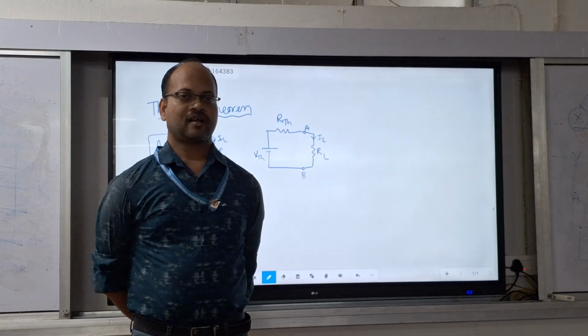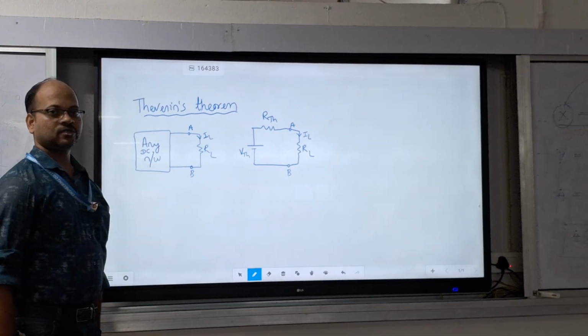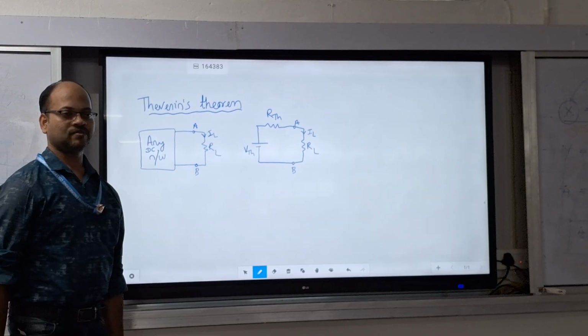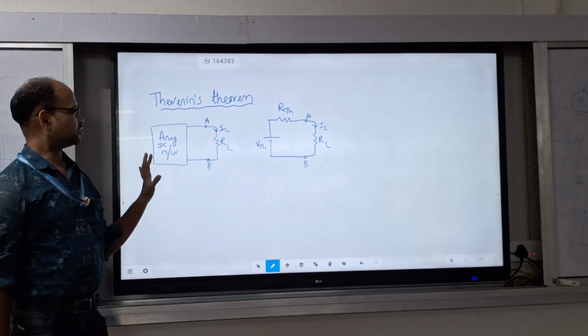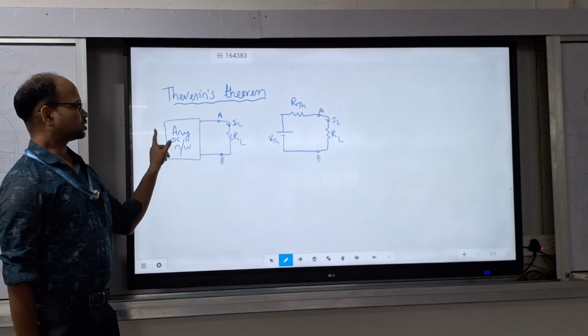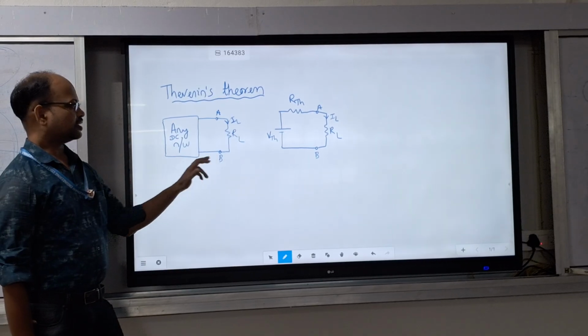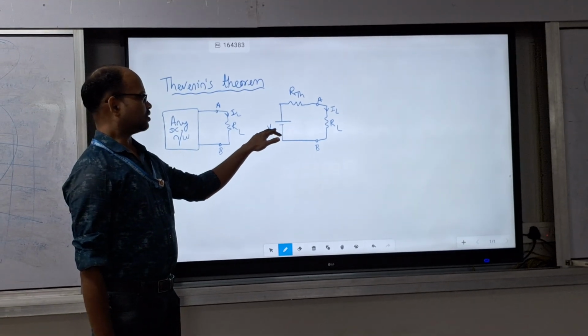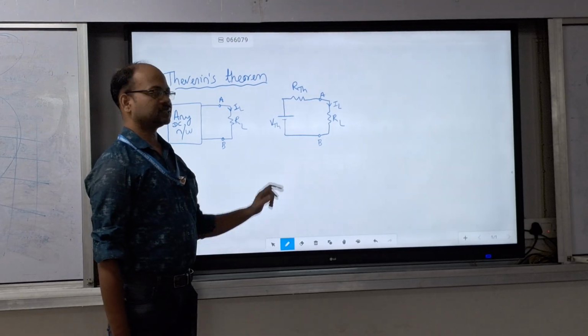Good morning everyone. I am Sangram, Assistant Professor of the Electrical Department. Today I am going to tell you about Thevenin's theorem. First of all, what is Thevenin's theorem? Here we study DC networks. Any DC network containing a voltage source, current source as well as load resistance can be replaced by this equivalent circuit containing Thevenin voltage, Thevenin resistance and load resistance.